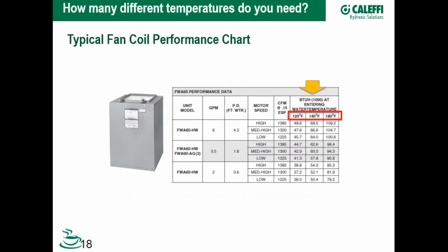Now, the first consideration, and actually this whole consideration, is based on what water temperature devices really need if I am designing the system and I have the option of possibly resizing equipment. So when I do a fan coil unit, most times people will say, I'm doing a fan coil, I need maybe 160, it could be 180 degrees Fahrenheit, as the number that everybody comes up with.